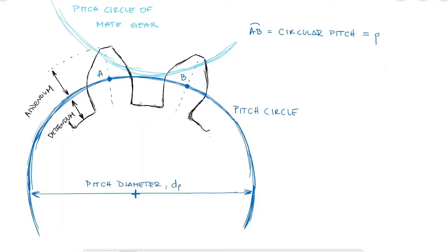Remember when you talked about the radius of a gear when working on simple angular velocity and torque topics in physics? Or the radius of a gear in a simple gear setup during your mechanics of materials torsion examples? What radius were you using then? Was it the distance from the center to the base of the gear? From the center to the top of the teeth? Even if you didn't know it then, it was a radius equivalent to the pitch diameter divided by 2, or just the pitch radius. So every time we refer to the diameter of a gear to talk about the relationship between number of teeth, angular velocity, or torque, we will be using this pitch diameter.